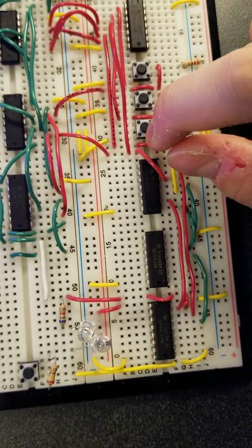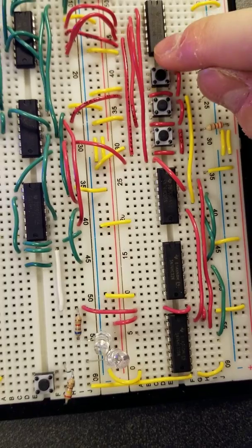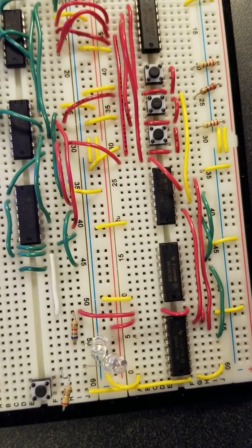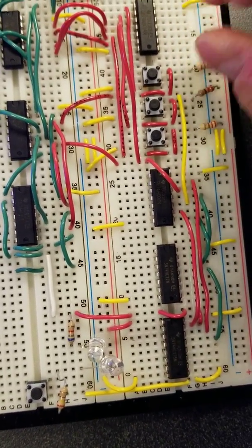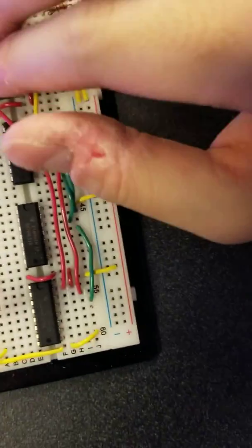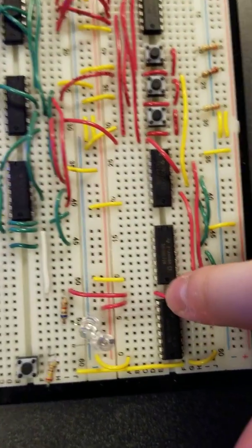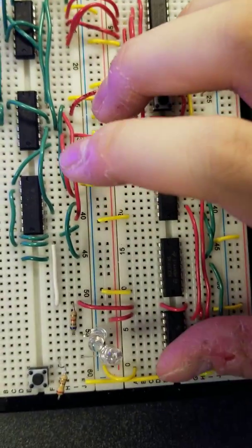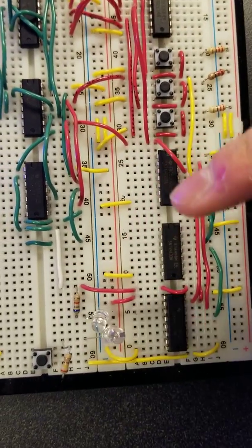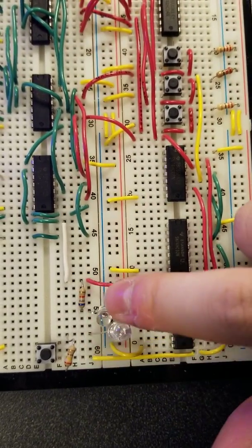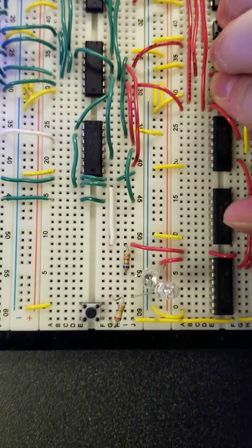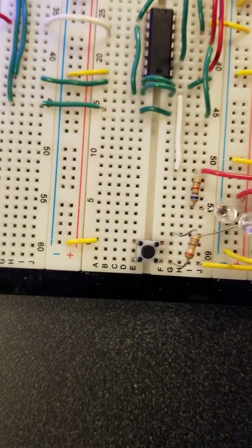So if the line tracker PCB were functional, instead of these 3 buttons, we would have the photodiodes from 1 and 2 connecting onto the circuit board and ANDed together with the AND gates, and likewise with 3, 4, and 5, 6. Anyways, going back to why this factor FSM is important, it is supposed to save whether it's the first or second intersection that we've crossed. Initially this Y output is going to start at 0, and once we cross the intersection, let's say we're going straight and then we cross it, this button over here is going to simulate the clock.